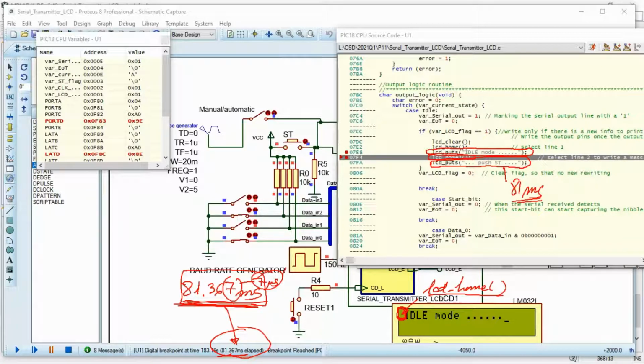So this device is all right, but it is a slow peripheral. It is quite slow compared with writing LEDs, for example. It is very slow. So what is it that we can do here, besides going writing once and again in the main loop? It's not so, right? It is a lot better if we write only when this flag is set. And when is this flag going to be set for writing something into the screen that takes that much time? Well, when there is new information to write, you see?